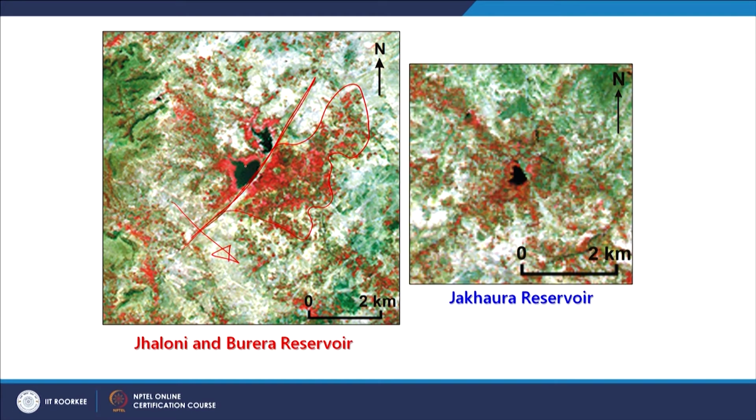Likewise, another example, and here what you are seeing in 4 directions, the water is available in the form of groundwater, and farmers are exploiting it to put on their fields. That one is in the northwest southeast, another one is in the northeast southwest direction, because these are the geological structures which are controlling. This northeast southwest is generally the trend of these quartz reefs, whereas northwest southeast are the geological dikes which are present there.